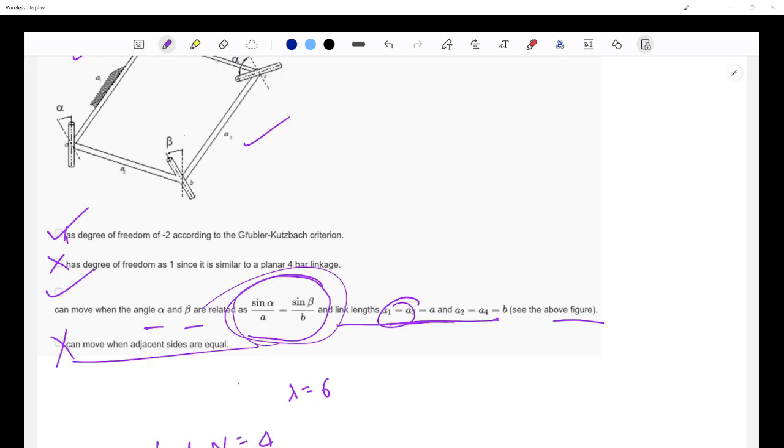You might mark degree of freedom equal to 1, and if you forget the angle condition, this is also problematic. So length equality is not enough, and thinking negative degrees of freedom means no motion is completely wrong. Okay, so as we saw in the earlier question, actual motion exists due to special geometry, and the Bennett linkage is a perfect example of constraint dependency, right?